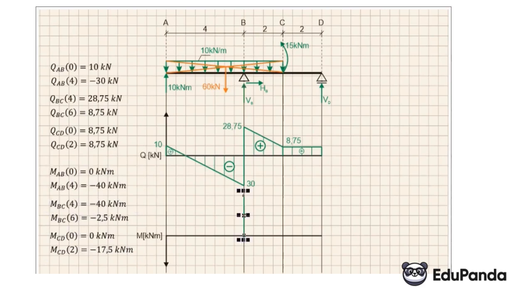And one more very important piece of information: if we have a change of sign on the shear force graph under continuous load, then we will have an extremum on the moment graph, meaning our shear force graph reaches a 0 point. So on the moment graph, exactly under this, as I made a dashed line, at this point on the moment graph, there will be a local extremum. And we need to calculate it because we do not know how this parabola will look. We do not know what the maximum value will be at this point. Well, we still need to calculate.